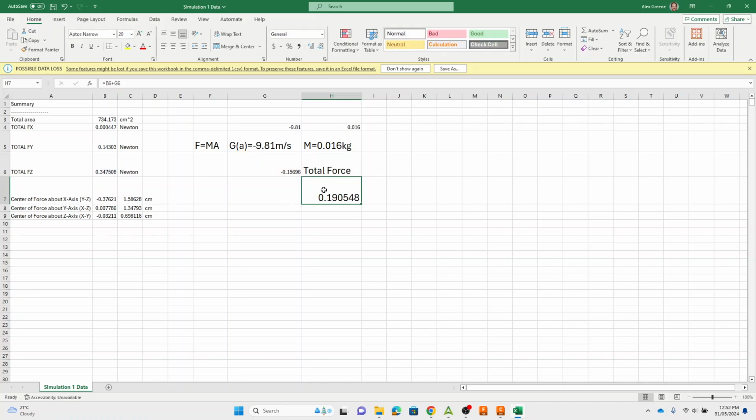There we go. So I'm generating positive 0.19 newtons of lift. So what I'm seeing here is my glider should fly, and that's how I can see that it should fly. There might be other minor changes that I'll make to make it fly better. That could be decreasing or increasing the angle of attack, and obviously changing the position of the wings in order to create a balanced flight. We know from our worksheets that we need to create balance and equilibrium when we're testing our flights.